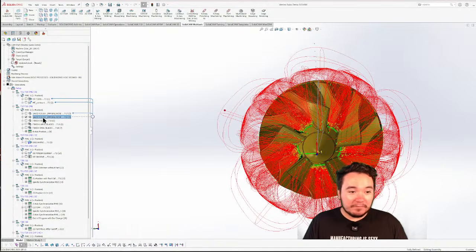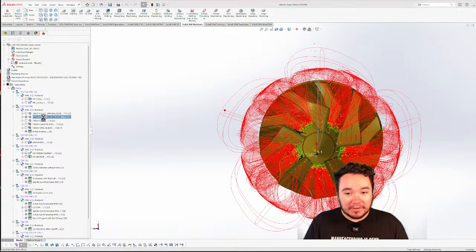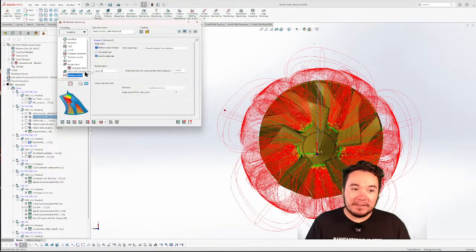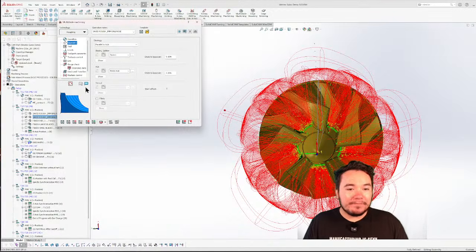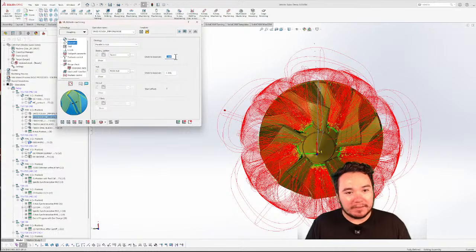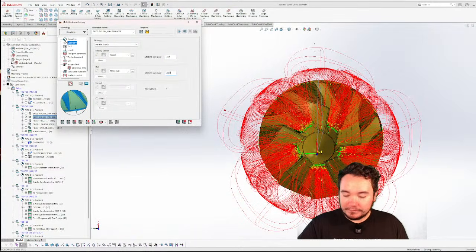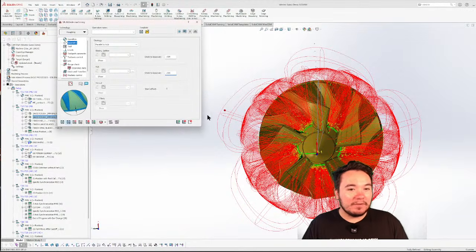As for the rough 1mm with the ball nose, just to clean it up a little bit, I just did a save and copy just with the tool change. So, and that would just go back a little bit further, a little bit deeper. I did change this. I was messing around with this earlier. I'll also actually switch that back to what I had it for the other one. 5,000. And we'll just save and calculate. Now we're gonna have to do it for everything.